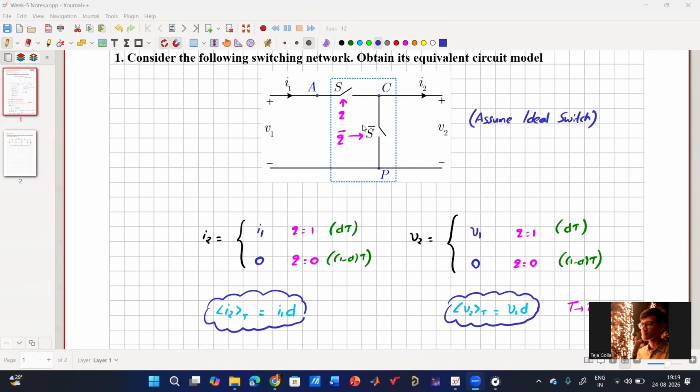It's a non-linear system because of the switching. If I write the inductor current in terms of this Q, then that's the actual original model where I am not making any assumptions. That is called the large signal model because it has the switching action as well as the ripple behavior in the model.